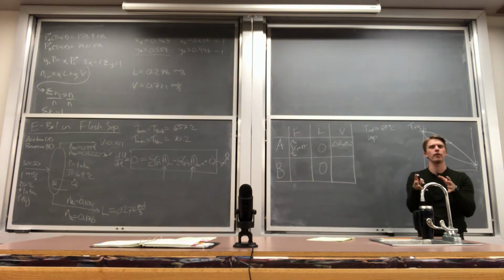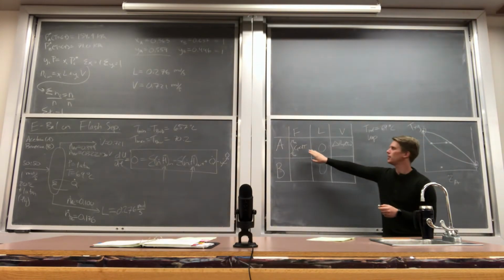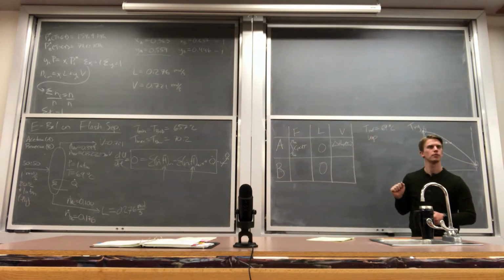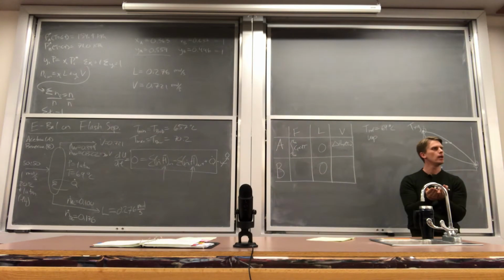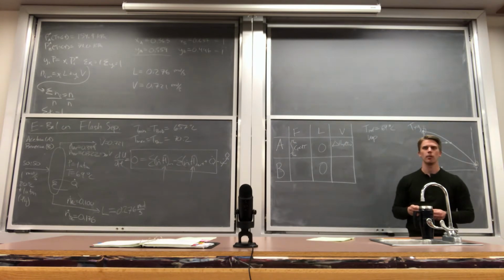So a collection of variables, pressure, temperature, phase, we wrap that up and we call it a state. So we're changing the state, in this case, from the reference state to the inlet conditions, or from the reference state to the vapor conditions. And how we do that is we just imagine that we're sort of lassoing or putting a balloon around an element of this fluid. We're transforming it through any arbitrary path that we've selected that allows us to get from one point to another. But that's called a state change.